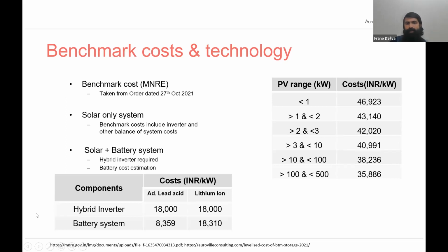At this point, we have understood the boundary conditions of our system, where we have realized that available metering mechanisms and the feed-in tariffs act as a boundary condition for the designing of our solar rooftop system. We have gone through a process where we have defined our consumption profile. We have understood how to allocate the consumption profile in the web tool as well.